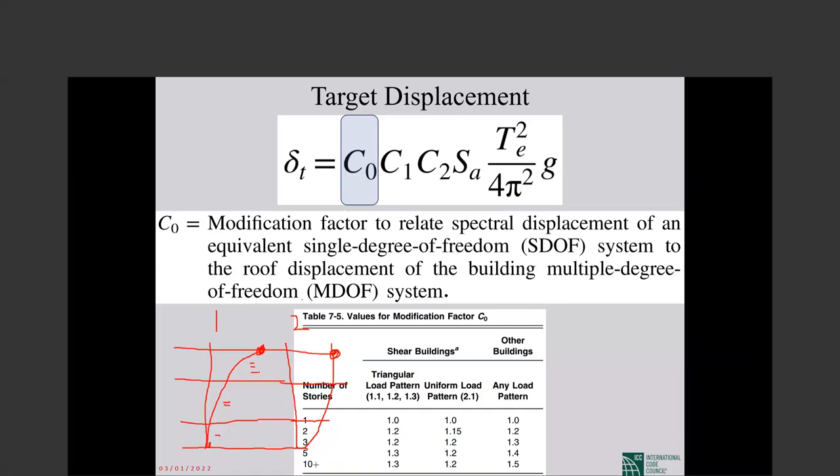So, for example, a shear wall system can't increase the stiffness in the upper stories because it's a bending type system. A bracing system can't increase the stiffness at the top. If you want to increase the stiffness in the bottom, this is good.